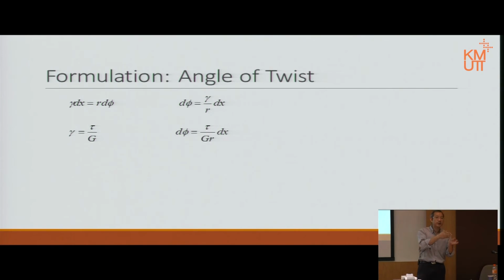So we will change the shear strain to the shear stress, and then relate it again to the torsion. The left-hand side is the elastic region for the shear, where G is the shear modulus, which works the same way as the Young modulus in axial deformation. Then we have changed it to this form. Then of course, as I indicated, we can change tau into the torsion itself, and then we have the final form.